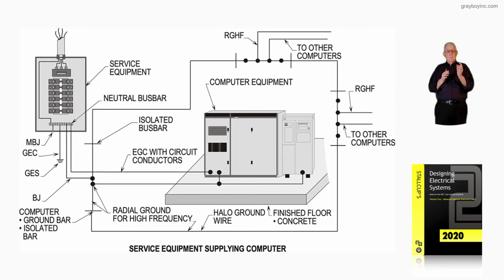If you're picking up noise from the service equipment connection to ground, as you see in the illustration, then again, about 2/3 of the way, 3/4 of the way from the equipment ground routing from the service equipment to the sensitive electronic equipment, it'll choke out the noise in such a manner that it will not create a problem to the operation of the equipment.